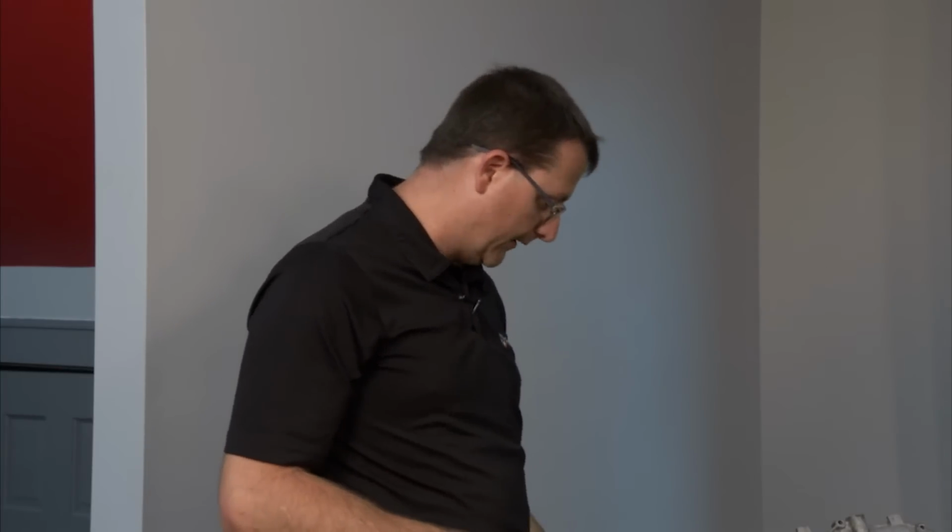And when you try to remove this scavenge pump, if you're doing this job in the car, you will quickly learn why I told you to pull the engine out of the car if it is a 911 variant. Removing this scavenge pump in the car can be done, but it is quite a chore. I recommend not going through that experience. Bite the bullet, drop the engine, and take advantage of a much simpler scenario.